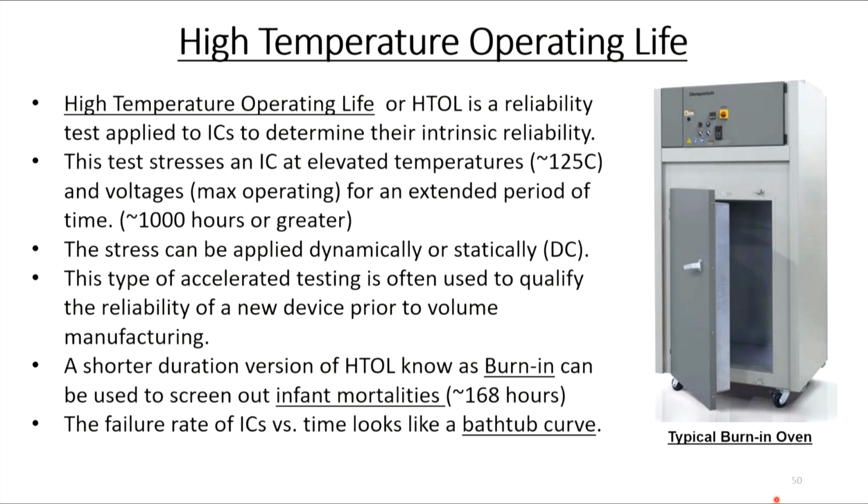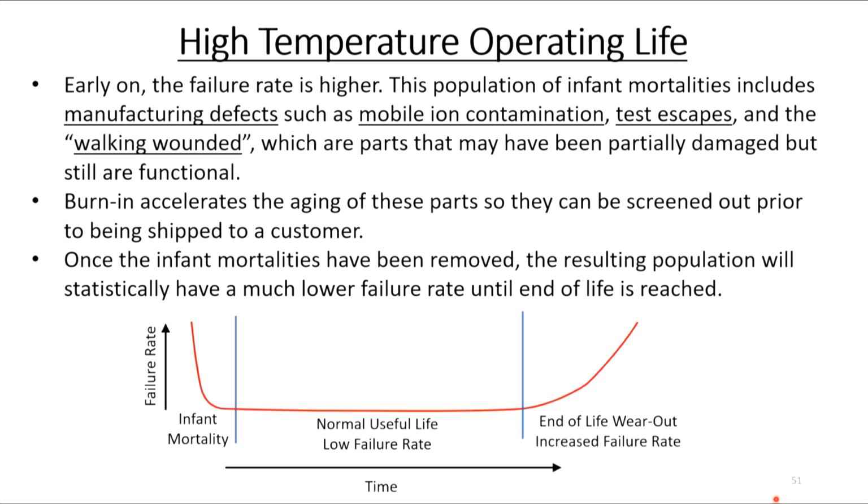So the failure rate of an integrated circuit versus time looks like a bathtub curve. And I show a bathtub curve down here. And basically on the y-axis, it's failure rate, and on the x-axis is time. So early on, the failure rate is pretty high. And this population is known as infant mortalities. And this can include manufacturing defects, such as maybe mobile ion contamination. You might have some test escapes in there.